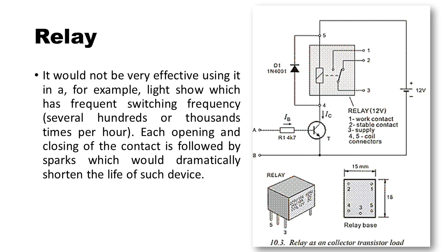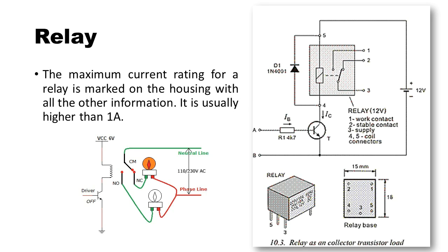It would not be very effective using it in, for example, a light show, which has a frequent switching frequency, several hundreds or thousands of times per hour. Each opening and closing of the contact is followed by sparks, which would dramatically shorten the life of such a device.